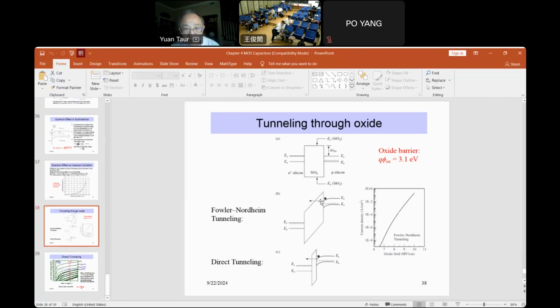This line is the oxide conduction band, and of course then it goes to the gate. But first to the oxide conduction band because of this tip. So the tunneling distance at a higher energy is shorter. This is a very important mechanism for the function of flash memory devices. We're discussing it in chapter 12, close to the end of this course.